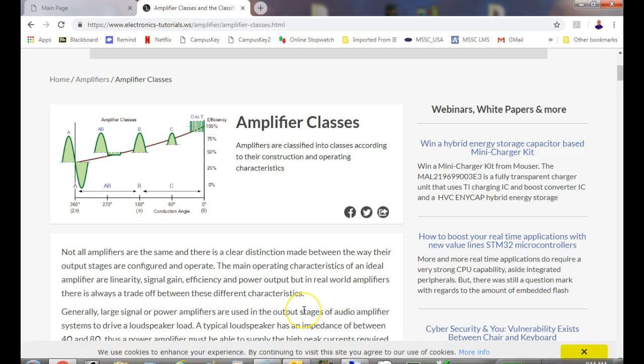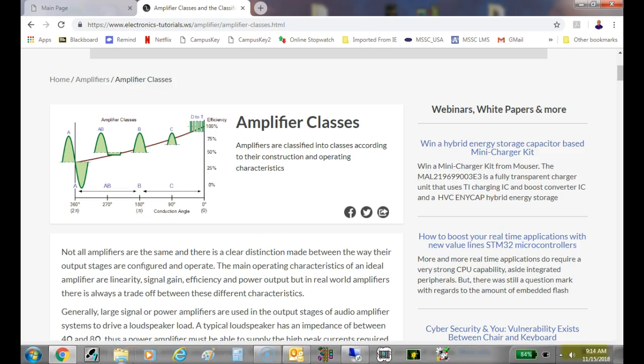Okay. And what we're doing is we're looking at half power. So if I'm sending 100 watts of power through a media, and on the other side I can get 50 watts of power, then it would be within its bandwidth. When it drops down to 49 watts, so you're losing 51 watts of power in your media, then we say that's outside the bandwidth. And this occurs, by the way, at what we call minus 3 dB. So we talked a little bit about dB in this class, right?